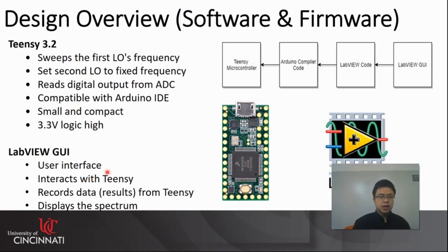On the software side, we use LabVIEW to design a GUI. This GUI is the main user interface to communicate with the Teensy, record the data from the Teensy, and then display the spectrum for visualization. Basically, the GUI is like the screen of the spectrum analyzer.